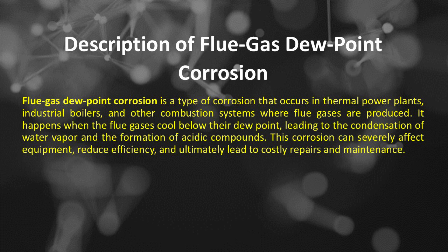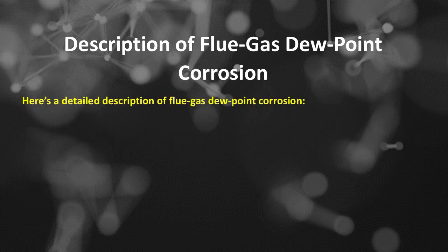It happens when the flue gases cool below their dew point, leading to the condensation of water vapor and the formation of acidic compounds. This corrosion can severely affect equipment, reduce efficiency, and ultimately lead to costly repairs and maintenance. Here's a detailed description of flue-gas dew-point corrosion. Number 1 is causes of flue-gas dew-point corrosion.